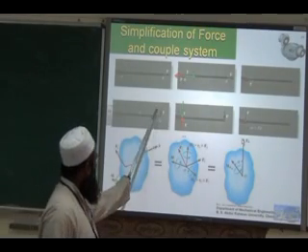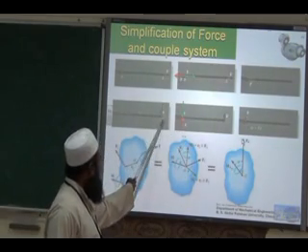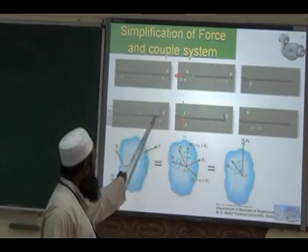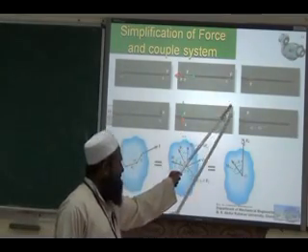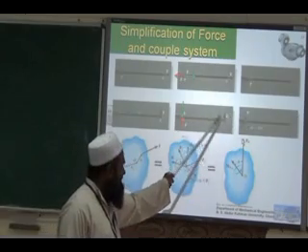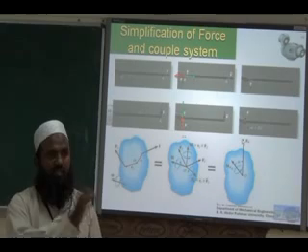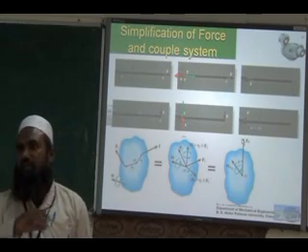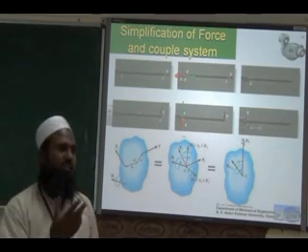But here, the line of action of the force is vertical. The line of movement is horizontal. So when you move like that, the force is transmitted, but it produces a moment also. We have got the force transmitted, but it will introduce a moment if the line of action and line of movement are different.